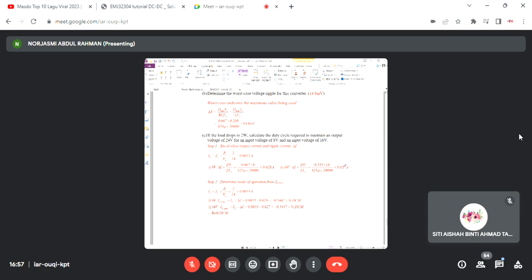during the switch on, the inductor will charge, right? During the switch off, the voltage will be the source voltage plus the inductor voltage, going to be the V out. So your question is, is I not equal to IL? Yes, it is the same. The current is the same.